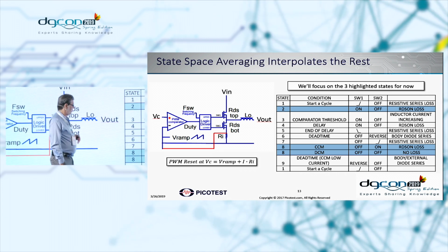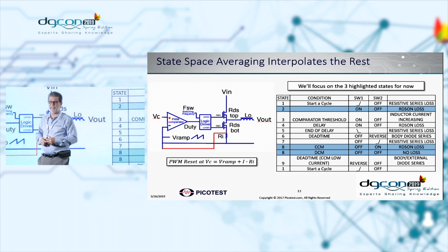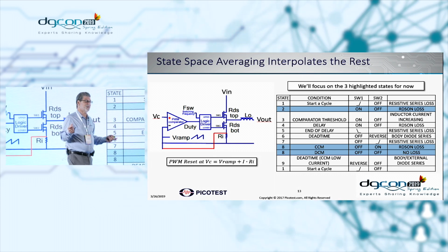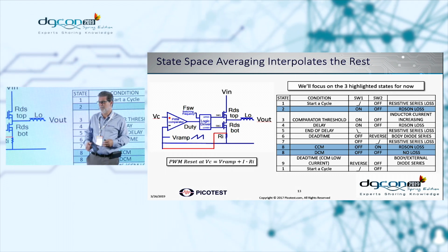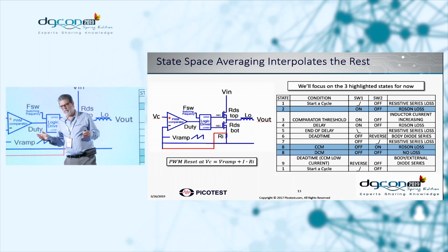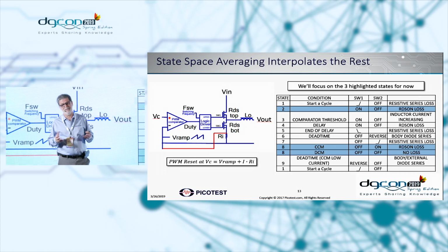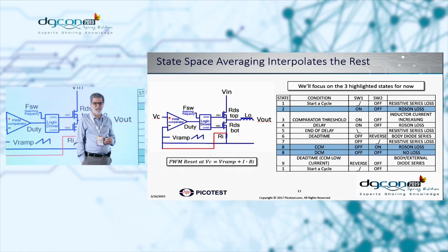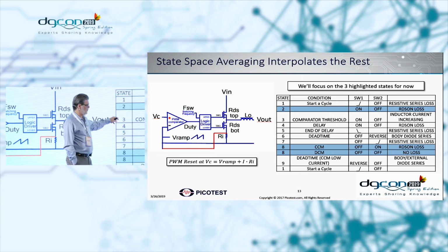In the real world, there are actually about 10 different states, right? We can consider this VRM to be a state machine. There's 2 states. The top MOSFET is on, and the bottom MOSFET is on. That's it, 2 states. In reality, there are many minor states in between those two. The transition times between MOSFETs aren't infinitesimally small. They do actually have finite times. And so if you wanted to average those times, you could.